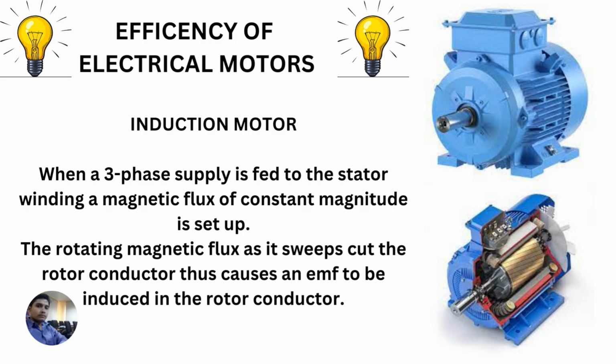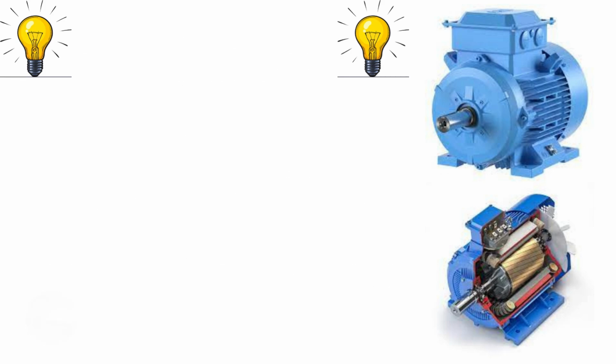Let us first start with the induction motors. Induction motor is the most commonly used motor in the industry. When a three-phase supply is fed to the stator winding, a magnetic flux of constant magnitude is set up. The rotating magnetic flux, as it sweeps, cuts the rotor conductor. Thus, it causes an EMF to be induced in the rotor conductor.